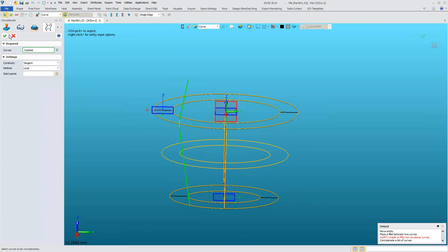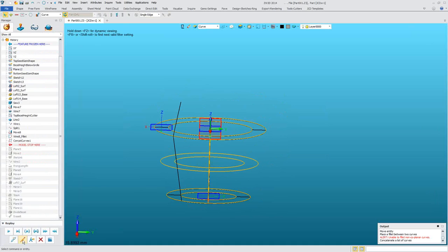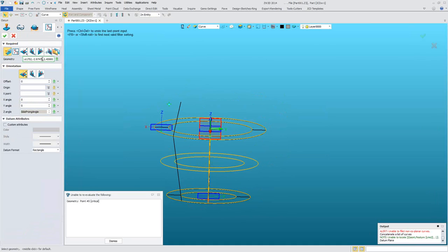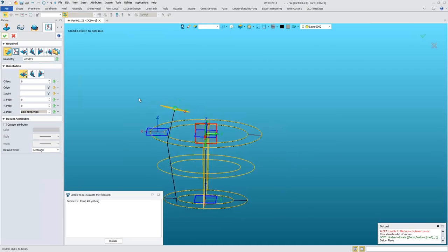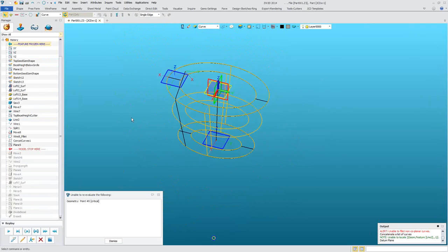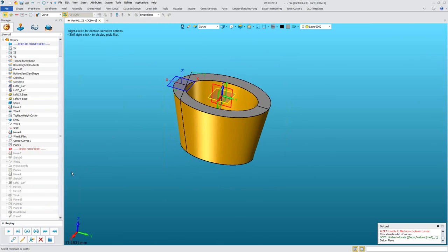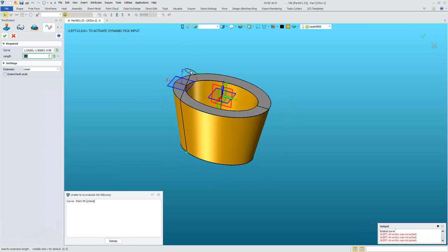So I'll force this tangent, and now I'll put the rest of history to use. Plane, geometry, top over here. Okay, I don't want a rectangle, I want just the XY. And we'll just put history to use now. Okay, move, sketch. Just pay careful attention. We have a new wire. It's down here. So we got to pick that wire.